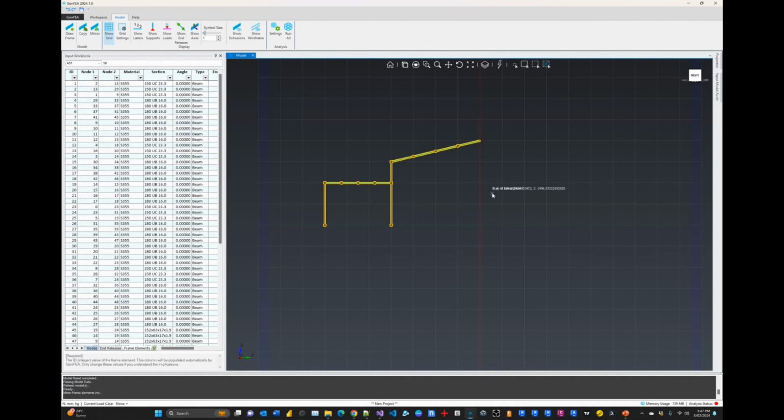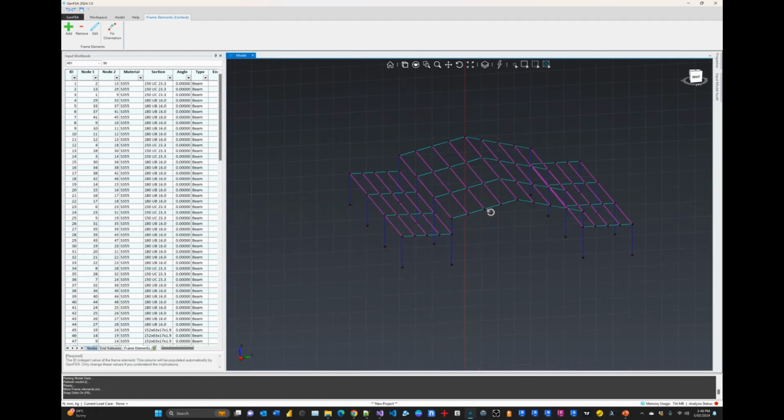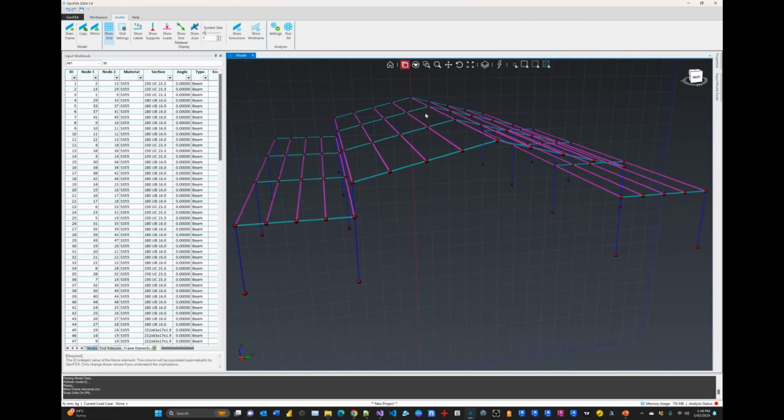Now I need to specify 2 reference points. So I'm going to right click and choose grid so I can snap to grid intersections. And I'm going to choose 2 reference points on this red axis as my mirror line. The program will now create the mirrored components, and it should only take a few seconds. Once that's finished, I'm going to switch my ortho mode back on again.